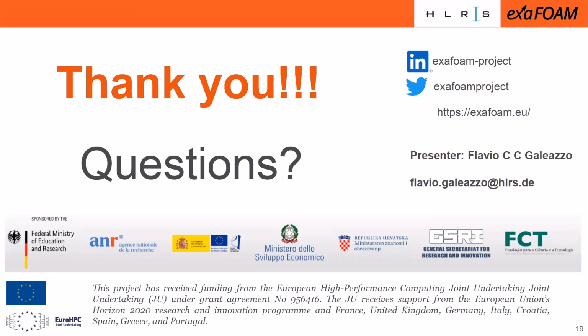Thank you, Flavio. So let's say the guideline for the users is to try to calculate this parameter according to their architecture and test cases. Exactly. My recommendation would be to test your test case on your architecture on one node, varying the grid size, and building this metric, you can see the optimal number of grid elements per core that's better for your system.